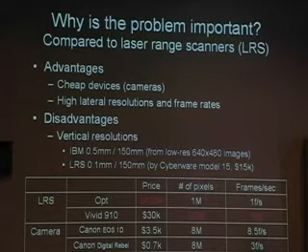But a couple of things to note: for this image-based modeling result, we use really low resolution images, 640 by 480. You can just use a higher resolution camera, maybe 16 megapixel or 12 megapixel, and then this result should become much better. Also, for a laser range scanner, typically if you want to get a single nice model, you have to scan from multiple viewpoints and then merge them into a single 3D model. So typically there's some manual work to register those depth maps, and additional errors can be introduced in that post-processing.